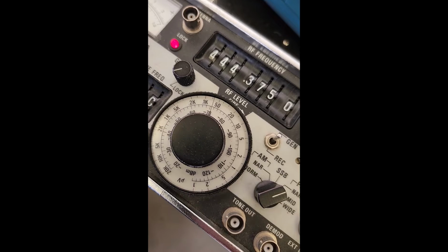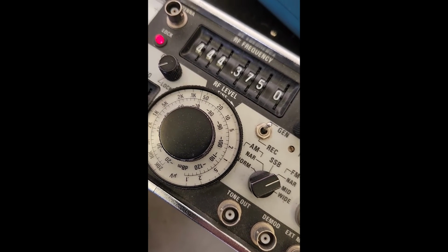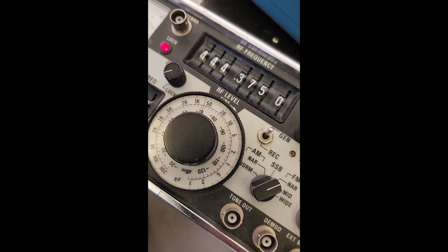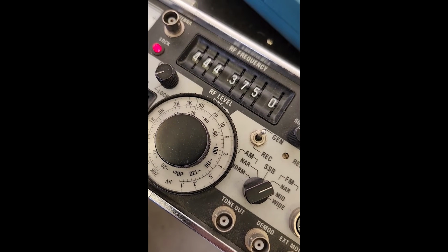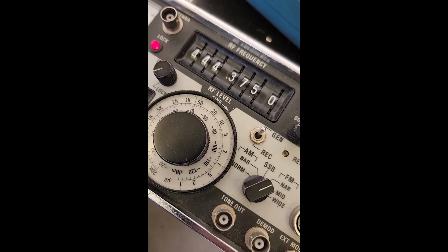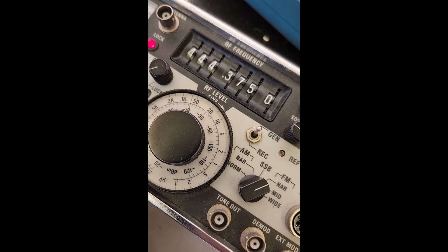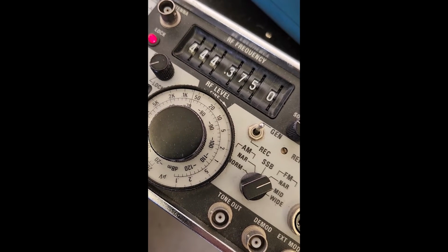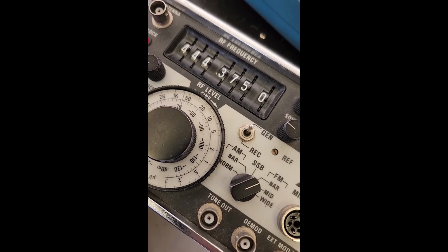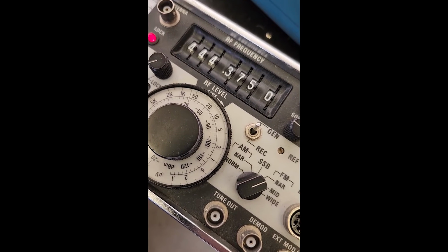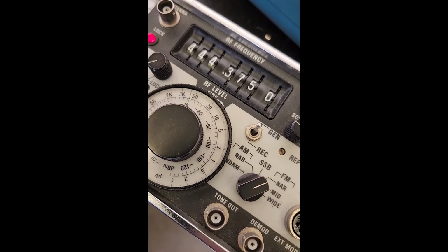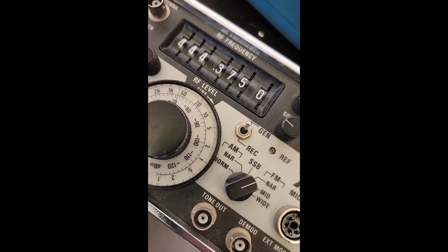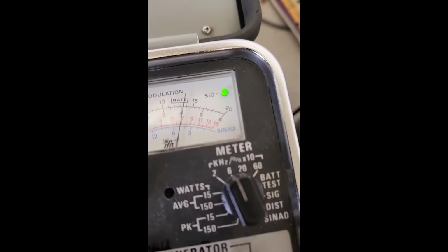Personally, when I'm setting up a duplex system, such as a standalone repeater, or two repeaters linked together at the same site, I like to add a little bit of gain on the deviation, just because many people have soft voices, don't speak right into their mics, and come through kind of soft. That helps give a little bit of boost there. So typically I like 3.2 going in and about 3.5, 3.6 coming out.